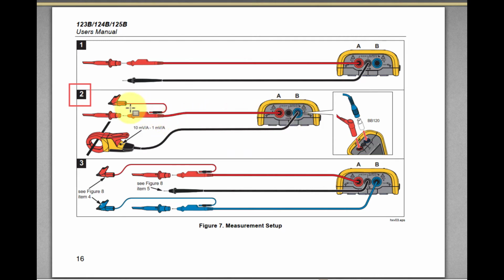And I just want to explain something. That little alligator clip and little J loop of wire that connects into that lead, you can either use it or you can use the common jack in the center. They are the same polarity. It gives you the option of using this little jumper lead with the alligator clip, and then the signal is shielded within that lead, and that is why they do that.